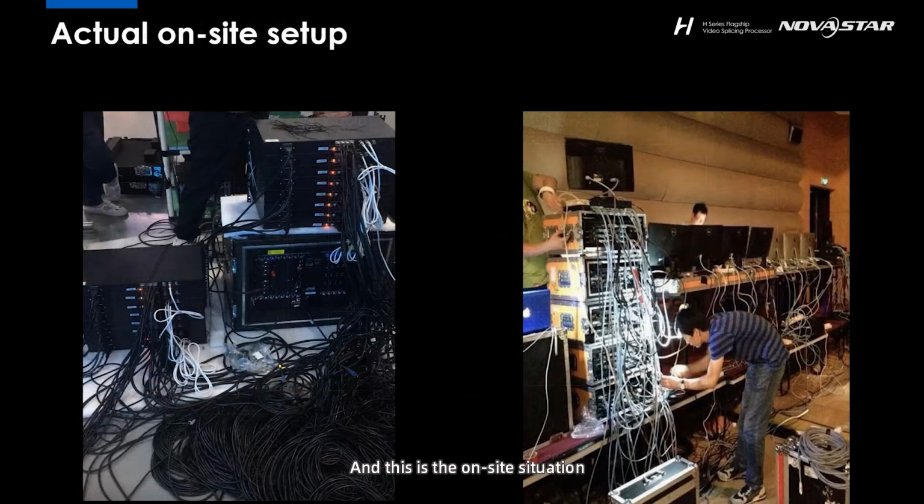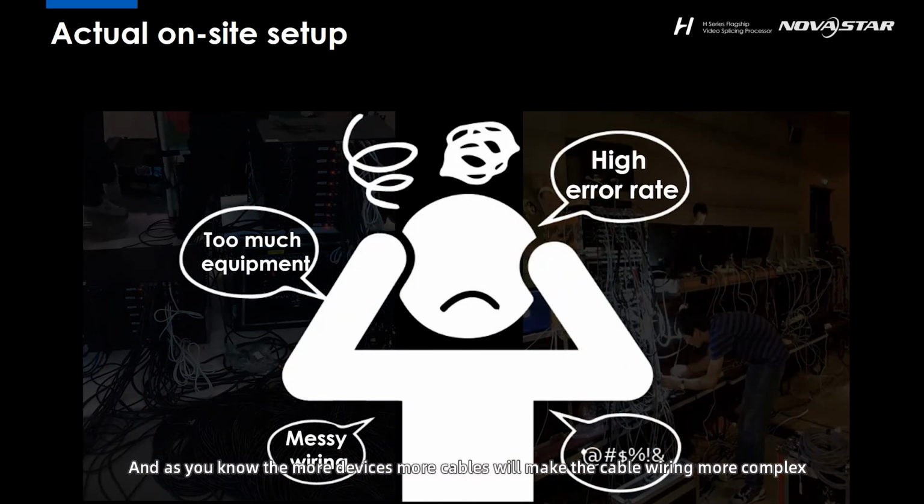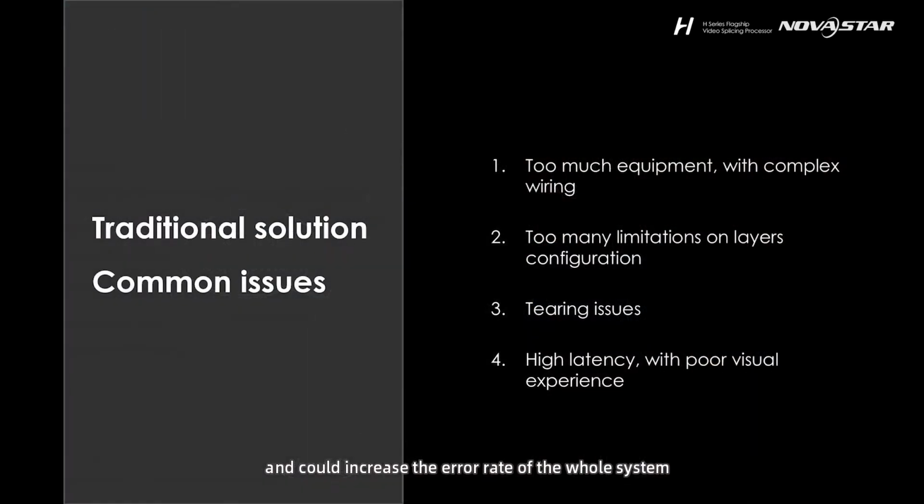And this is an on-site situation. There are too many cables: Ethernet cables, DVI cables, USB cables, etc. And the cable is killing me. As you know, the more devices and more cables will make the cable wiring more complex and could increase the error rate of the whole system. And we may face a video tearing issue between several outputs of the video splicer, and more devices for sure will cause high latency. And with the layer configuration, we'll also have too many limitations. So whenever I think about this situation, I get a headache.